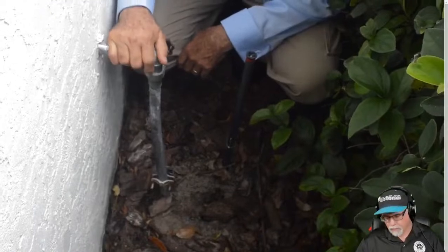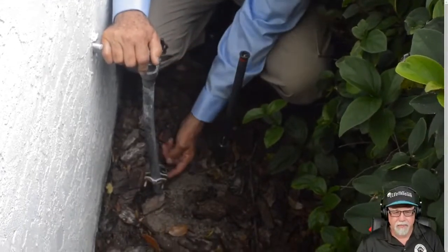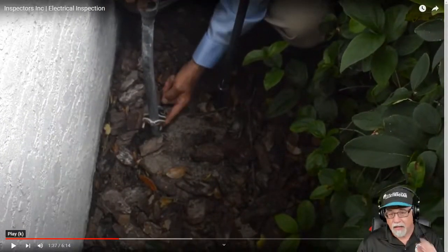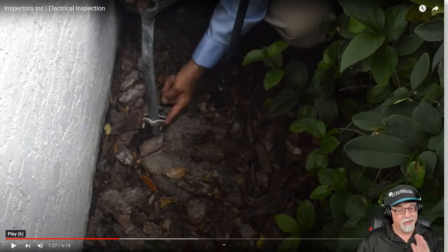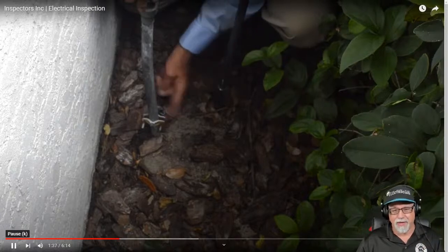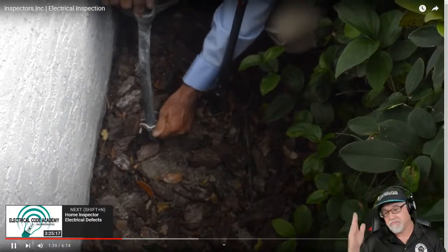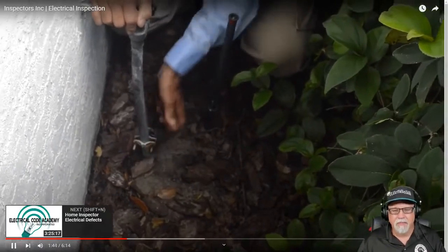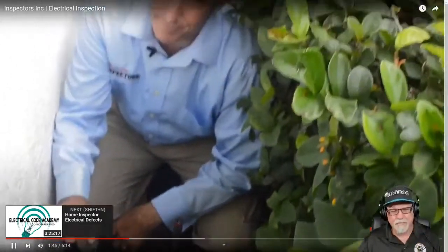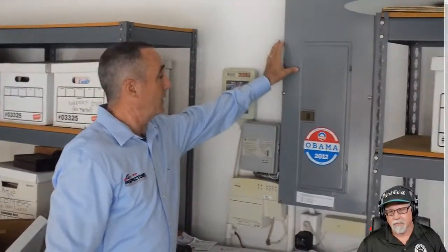Okay, so this is the copper pipe coming into the house, and if you'll notice, there's the ground wire. To be honest with you, that doesn't look like copper to me. I'm just saying. Doesn't look like copper, but here we go. Okay, and it's clamped directly to the pipe. We do check to make sure that these ground clamps are nice and snug, because if they're not snug, guess what? No ground.